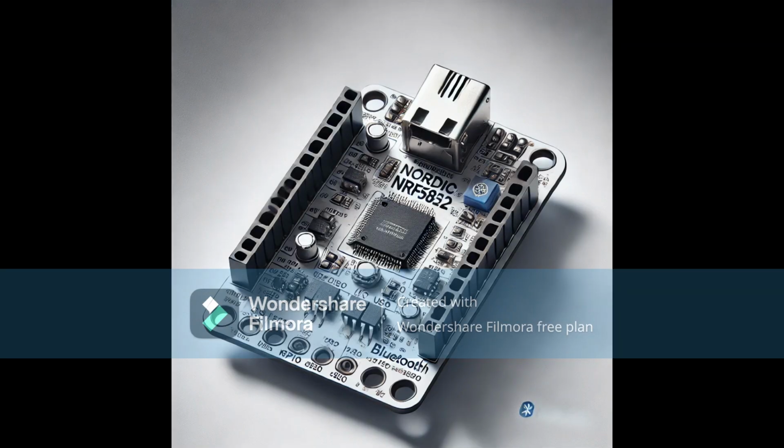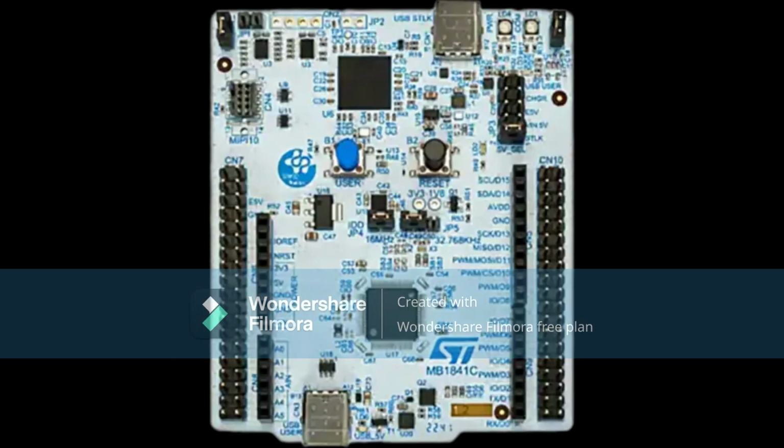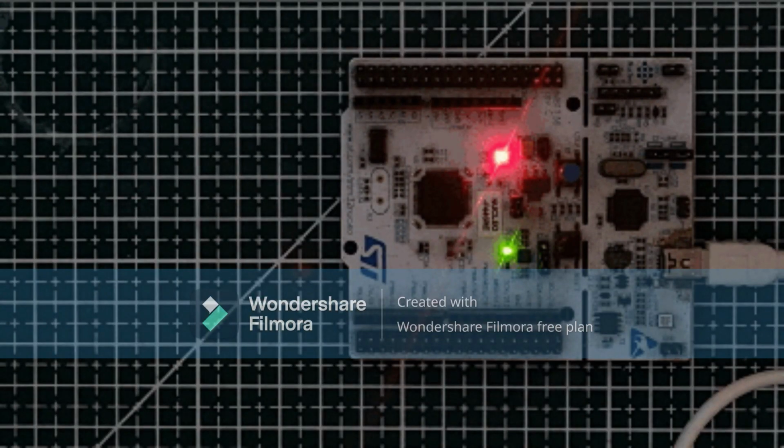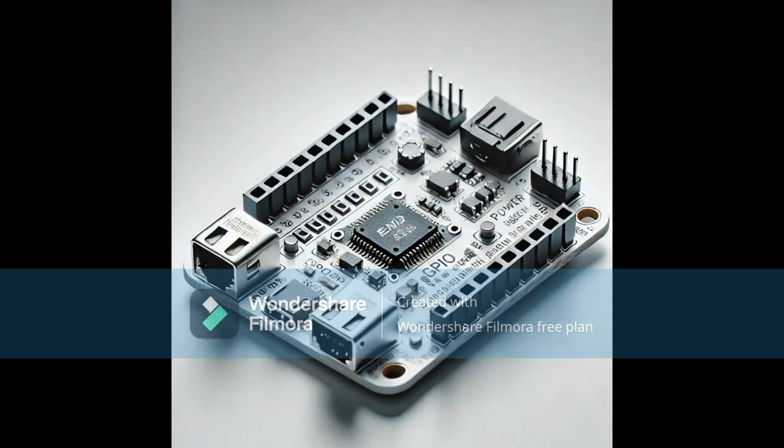Depending on the supported debug system, it is possible to connect a debugger to the device, and here are two examples. SWD, Serial Wire Debug, which can be added using two pins. It is designed for micro debugging. JTAG, Joint Test Action Group, with 5 or 4 pins. It is designed for checking faults in boards in production.